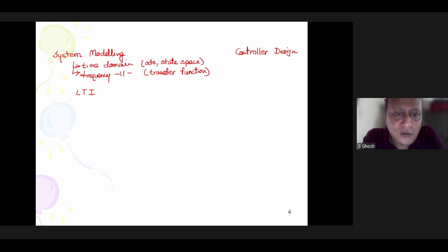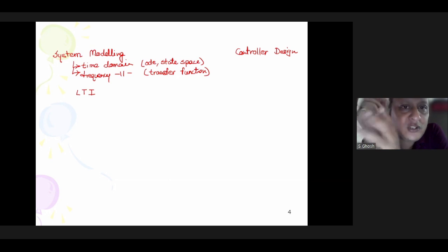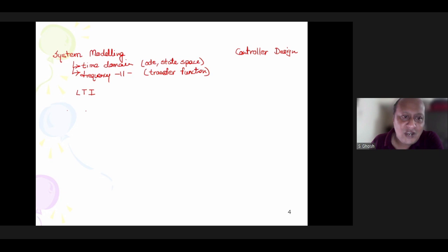Right? So, like the people who are working on power electronics, if you have to design a controller for a converter, now a converter is a non-linear system because there is a switch involved there, which is making it non-linear. Now the problem is how to design a controller for a non-linear system. Okay. Now, what basically we have to do, that non-linear system, first of all, we have to represent it by a model. So most of the times what we do is that particular non-linear system, we approximate it to a linear system and then we design a controller. Now the problem is, suppose you